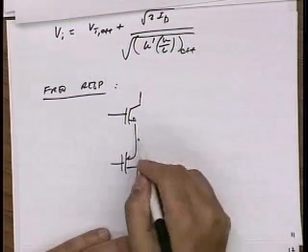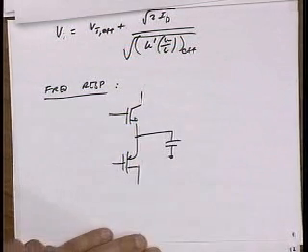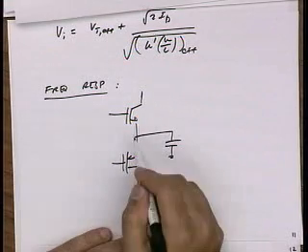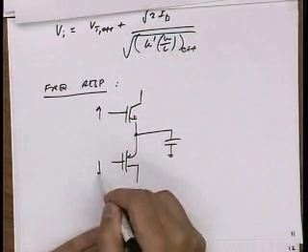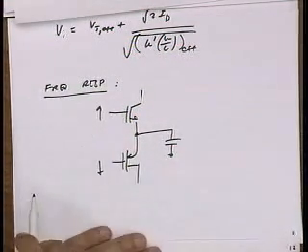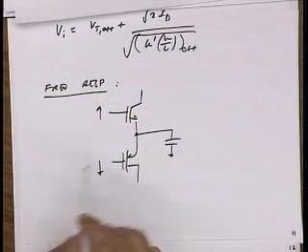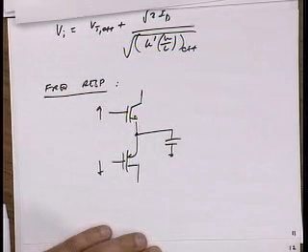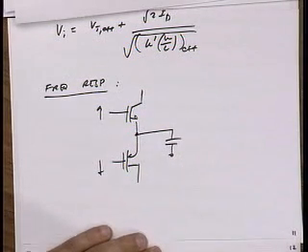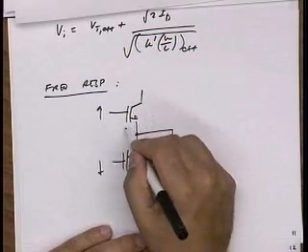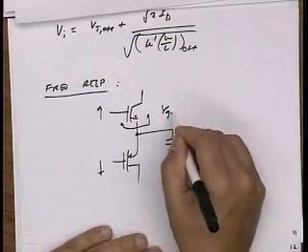Well, it creates a virtual ground, right? If I actually drive this circuit, this is a differential circuit. If they're sized to have the same GM, this point doesn't move, and so I have a virtual ground, and then this capacitance doesn't matter. All right. So what I want to do is equalize the GMs.